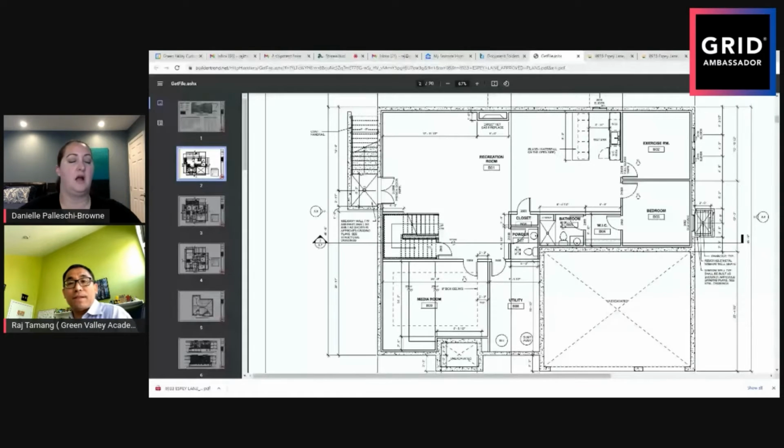Does that make sense? So if somebody says basement plan, you're talking about the architectural plan. Somebody says foundation plan, they're not really looking for the layout and stuff. They are looking for structural information on the foundation: how wide the footing is, how wide the concrete wall is, what the reinforcing is, how thick the footings are. All that information would be in the foundation plan.